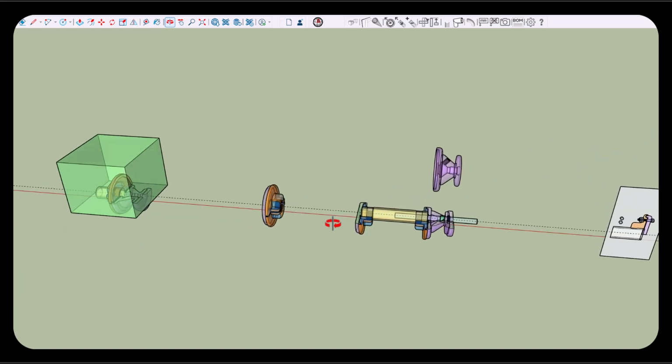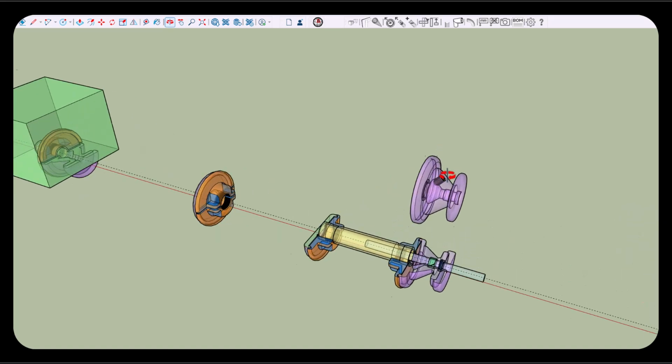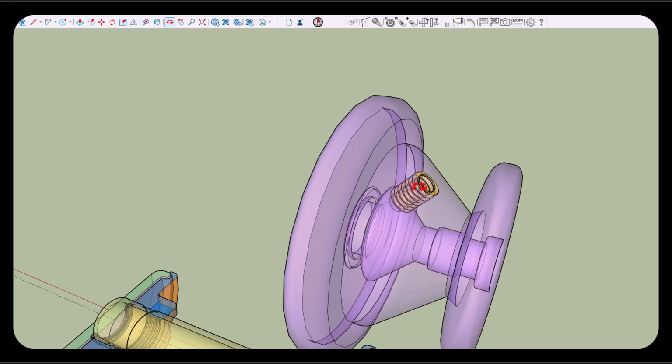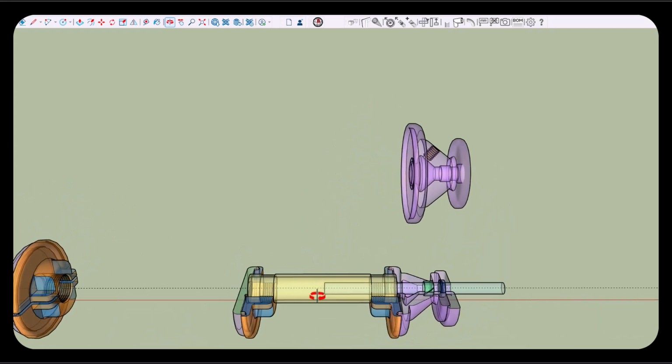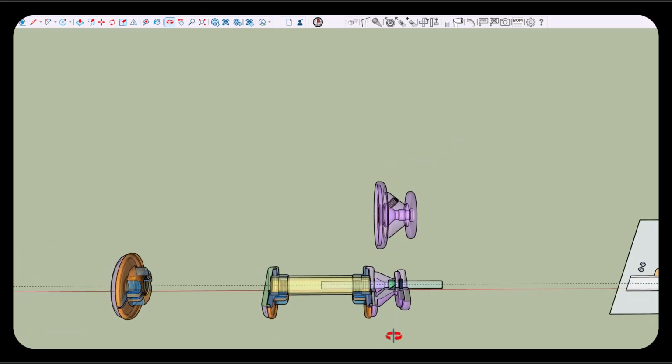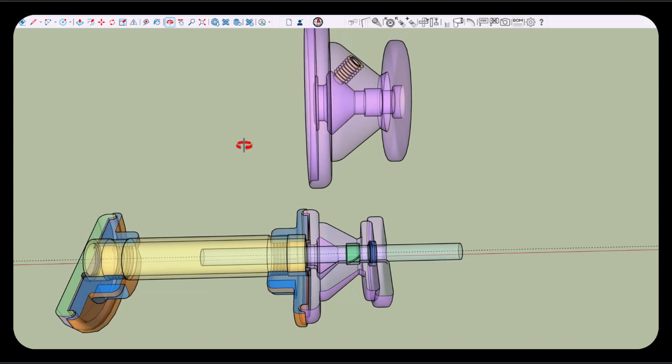And the way you put fluid into the other end of the hydraulic cylinder is with this: you drill through here and then tap it. And then we're going to have some pistons in here. I haven't done anything with the pistons, but oh, and so remember, everything is times 10.